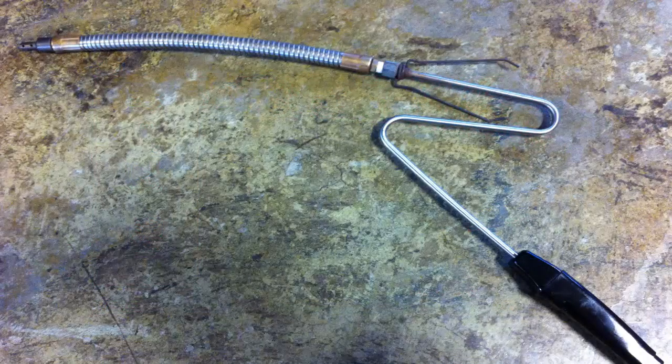I'm placing the exhaust probe on a table during analyzer and engine warm-up. We can measure the gases before the catalytic converter, or pre-cat. A special tool can be used to punch the pipe, allowing us to use a needle probe on our gas analyzer.